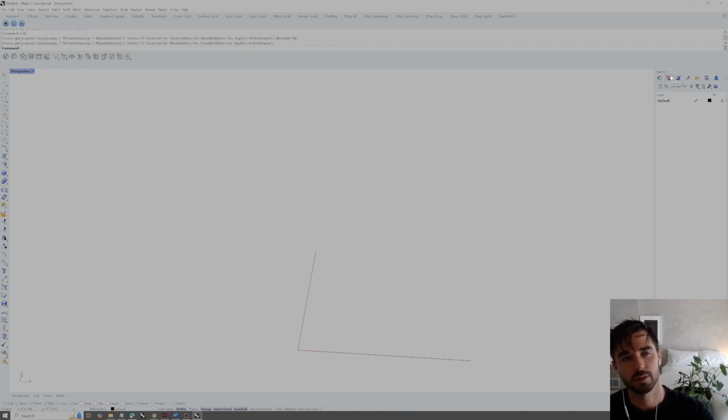The next major tab here is the layers tab. So right now we just have one layer. This is going to be our primary scene outliner for Rhinoceros 3D modeling. So right now we just have default. If we wanted to add an additional layer, we can do that by clicking new layer, and I can say geometry samples and then click away, and that makes a new layer called geometry samples. We can edit the color or material of things on this layer by changing the information over here to the right. We can also toggle visibility or lock it if we no longer want to edit whatever is on this layer.